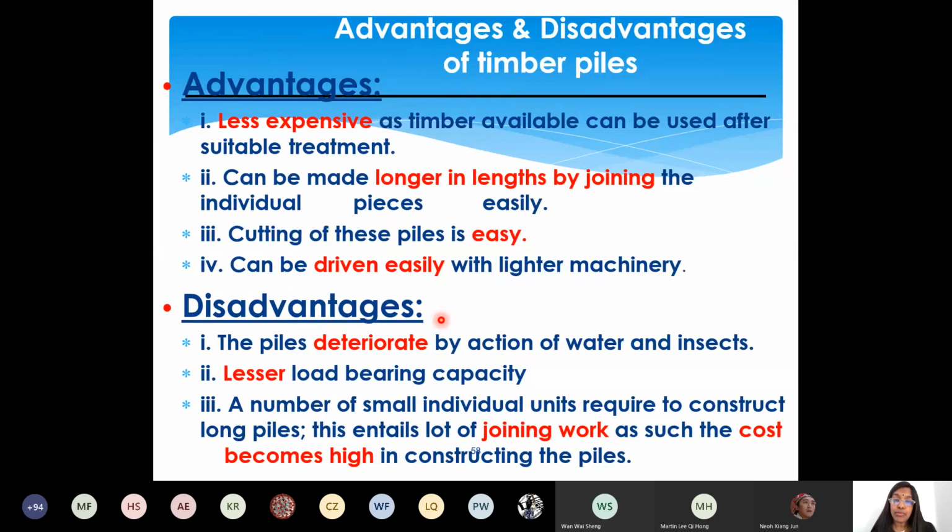Advantages and disadvantages of pile foundation. All of you know that this is less expensive, affordable. Timber is available, and can be used after suitable treatment. Care should be taken to avoid honeycombs, termites and fungal attack. It can be made longer by joining the individual pieces easily, right? Proper bonding can be created by screwing, by hooks, and by proper brackets and proper nailing arrangements.